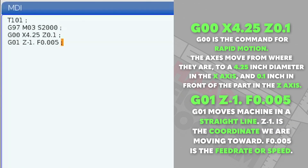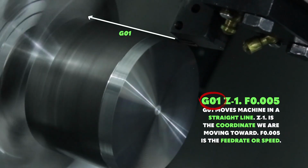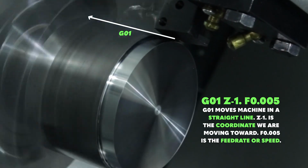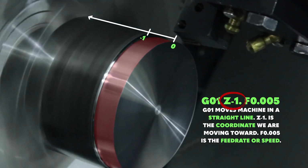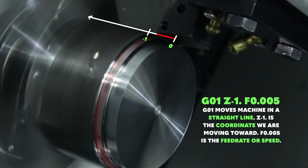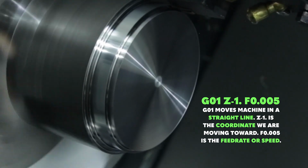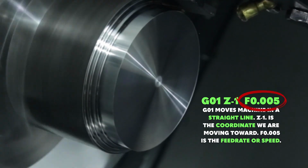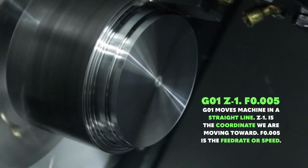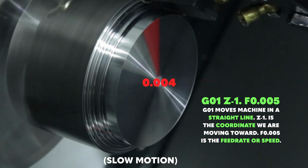Next is the G01 command. G01 tells the machine to move in a straight line to a new position at a specific speed. Z-1 inch is the coordinate we're moving toward, and the F address code and the .005 value specifies the feed rate, or speed at which we'll be moving, in inches per revolution. The Z-axis will move .005 inches with each revolution of the spindle.